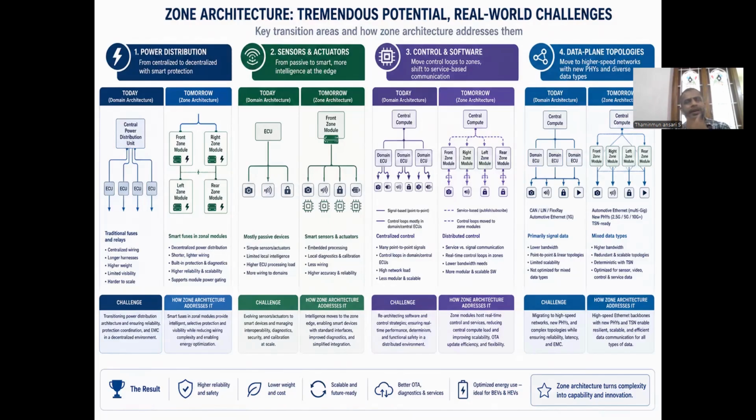In smart fuses, they use transistor-based circuitry which acts as a fuse to shut down the power of the ECU module when there is an overcurrent. That is the advantage of these smart fuses. Again, it is resettable. If there is a failure in the fuse, in the traditional sense, we have to remove that fuse from the device and then fix a new one.